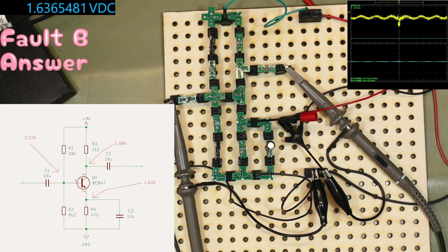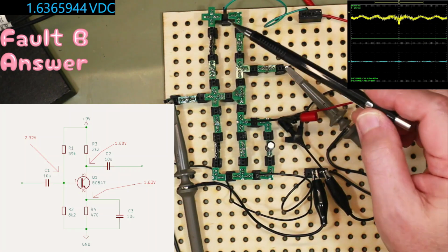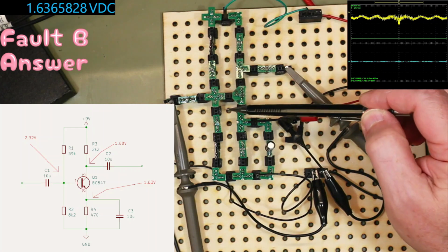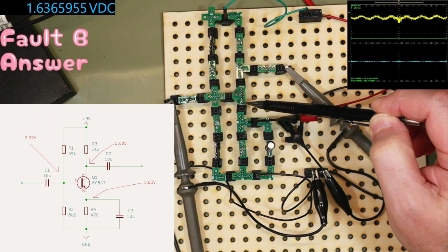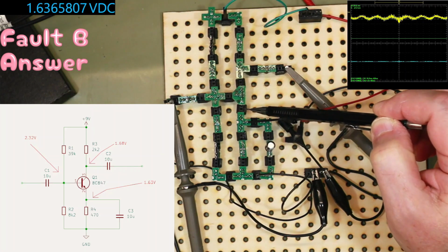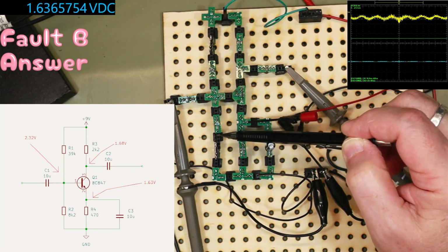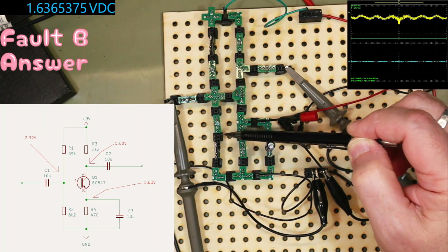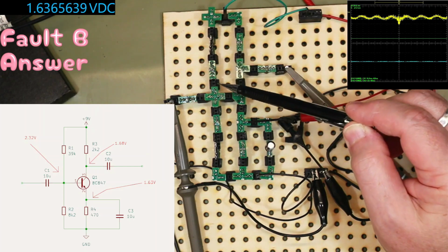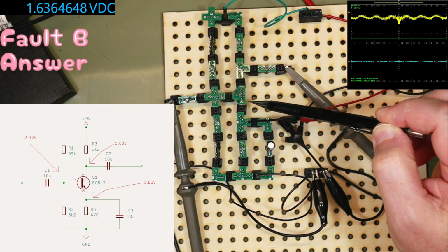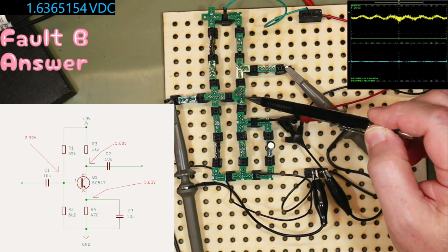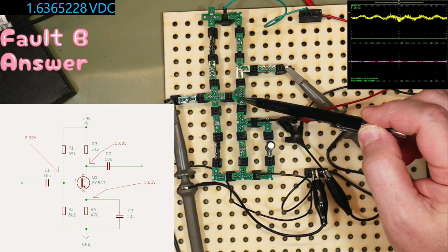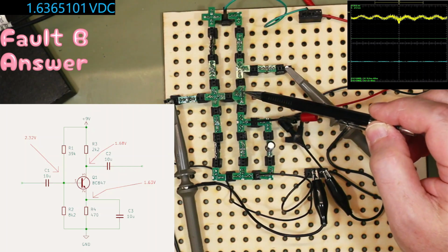Well, again, this is an R1, R2 problem. It's a biasing issue. Normally there's enough current flowing down here, and some current flowing through into the base, so that you bias the transistor correctly. So what's happened? Well, we've lost R2. R2 is no longer there. So all the current that's flowing down here is trying to go through the base. Now the base current is going to be limited by the current gain. The HFE, or the current gain of this transistor, is the limiting factor. And so it's got into full saturation.